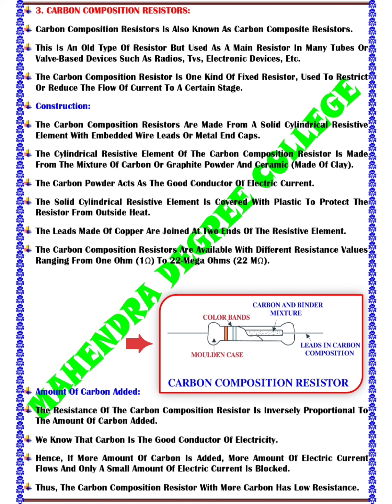Then, a coating is applied on the resistor to make the resistor body non-porous. The resistor body is cut into lengths for the required resistance value. For different power rating resistors, the diameter is varied to vary the heat dissipation.